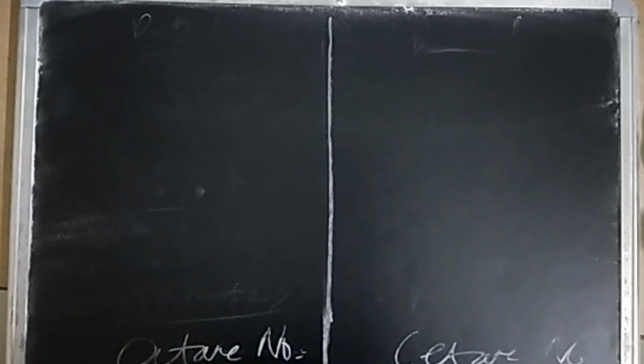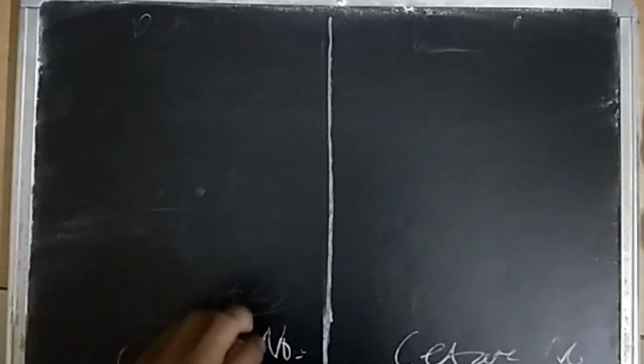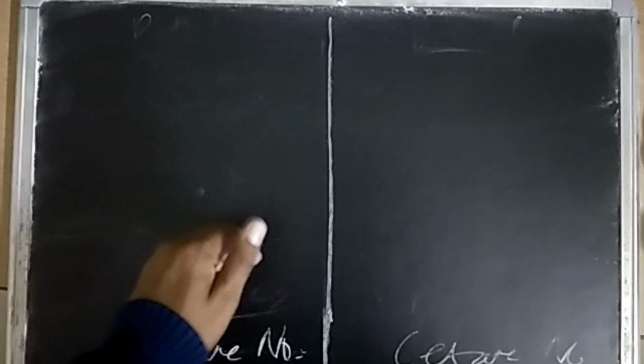Octane number is a number that characterizes the petrol fuel, and we know that with high aromatics there will be a high octane number. It's just the proportion of N-heptane and octane. If the octane is more, that means less knocking and a more stable engine. So we will prefer a higher octane number.